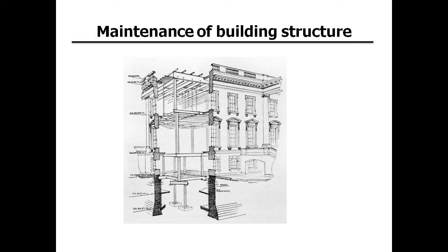And overall, the external envelope of the building, which is your roof, your external walls, windows, doors, it's most important that these are easy to maintain, easy to access, and that they have longevity in providing a good service and keeping the building watertight. Water ingress means internal finishes will deteriorate. There can be building sickness, encourage termites, rapid deterioration, and all these things lead to loss of tenants.